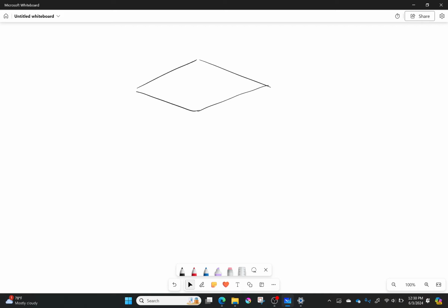Now we have to give it some values here. First off, we need to realize it's supersonic. It's going this direction. The flow is going that direction. And so it's going to have a shock wave going off the front. We might also realize it's probably going to have some expansion fans right here as the flow turns. And then finally at the back, it would have some more oblique shock waves. Okay, not too bad. But we still need to define a little bit more about it.